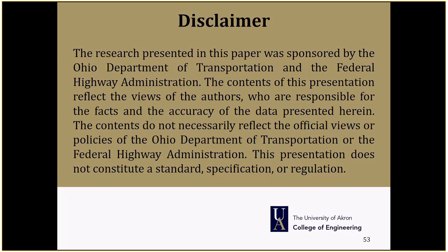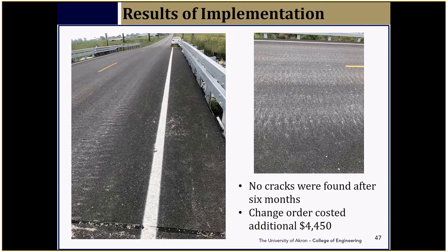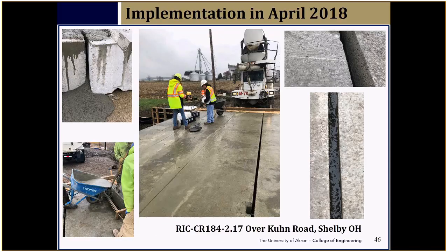You need a paver. Well, I think that's possible, but in some cases, the tops of box beams were fabricated with shards that penetrated the membrane with any kind of weight on top of it. That's fixable. I think if a contractor paves on top of it, if it's adhered well, and if the top of the mat is clean, you stand a pretty decent chance of paving on it without destroying the membrane. But he didn't show you all the pictures, and some of the pictures I saw had rocks on top of the membrane. Contractor.